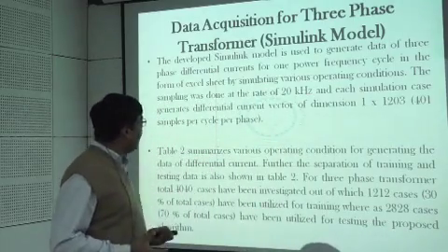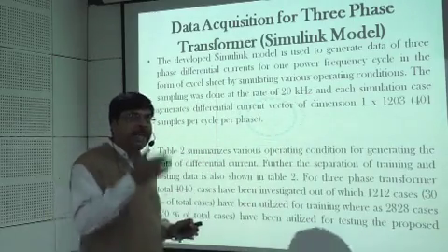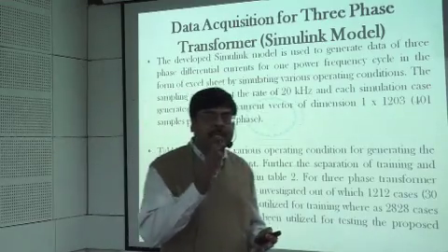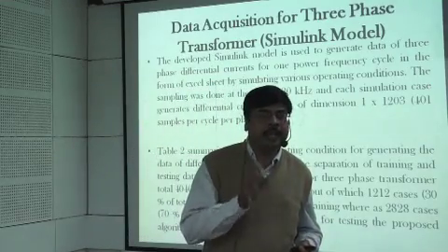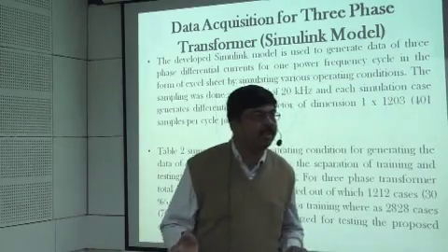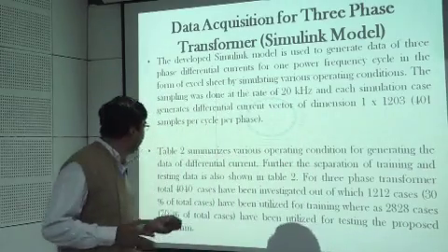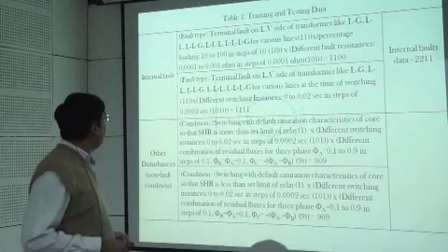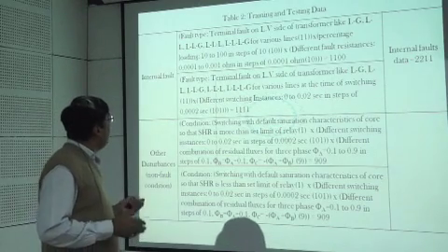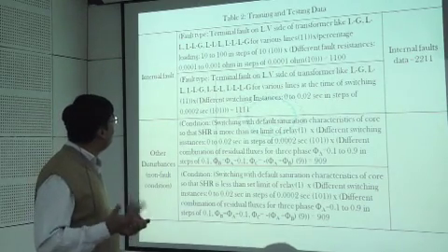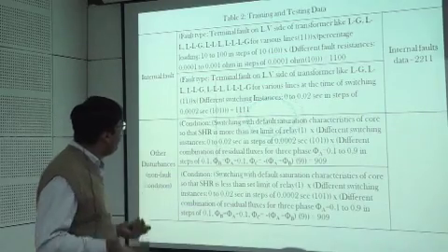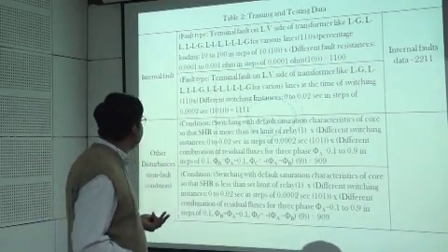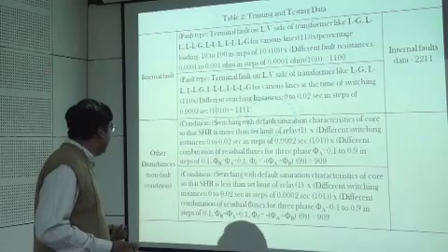Here I have collected data again for one cycle, and in differential I am taking decision based on the data of three phases. This means I will have data of three phases. This table shows the data, like for internal fault, I have performed a terminal fault on the LV side with various percentages of loading, various fault resistances, and various switching instances.